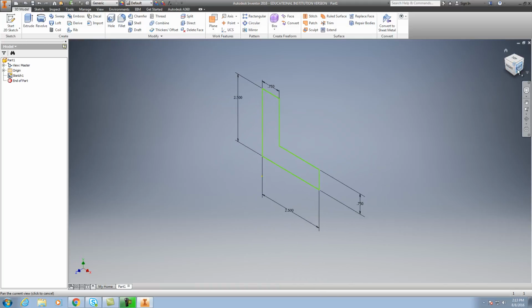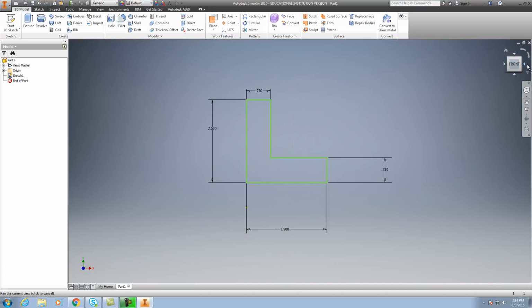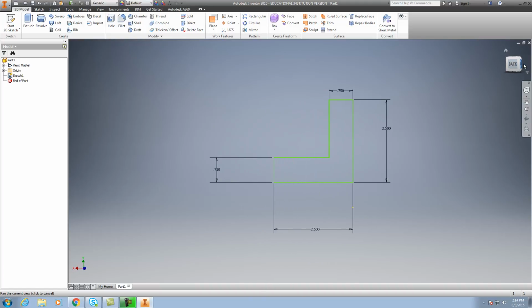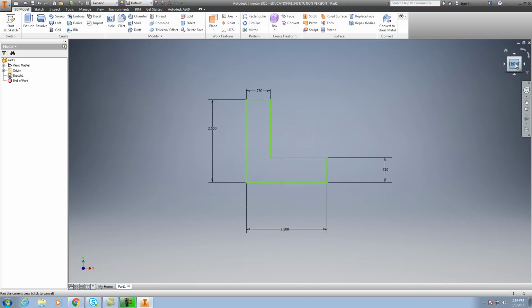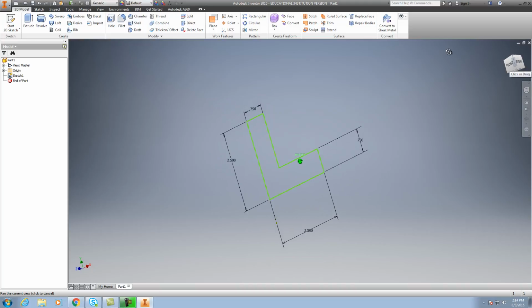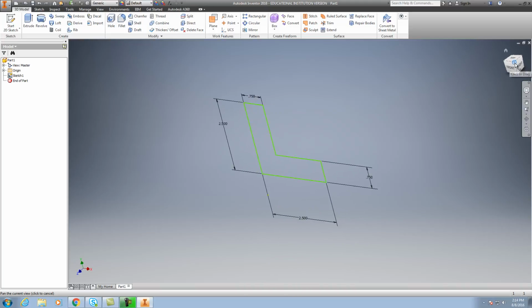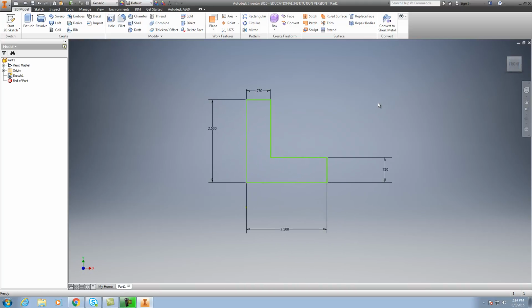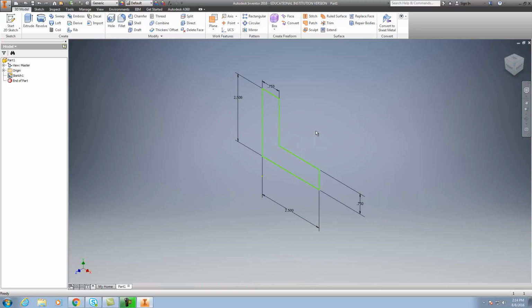You click there, click to the right hand side, you just can't see it. You're seeing an edge view at that point. Keep on turning it around. I'm just smashing with my left button, and I can twist this thing and holding it down. Twist it. Now, what I want to do, I want to put this in an isometric form, and I want to add my 3D depth. And the button I use is called extrude.